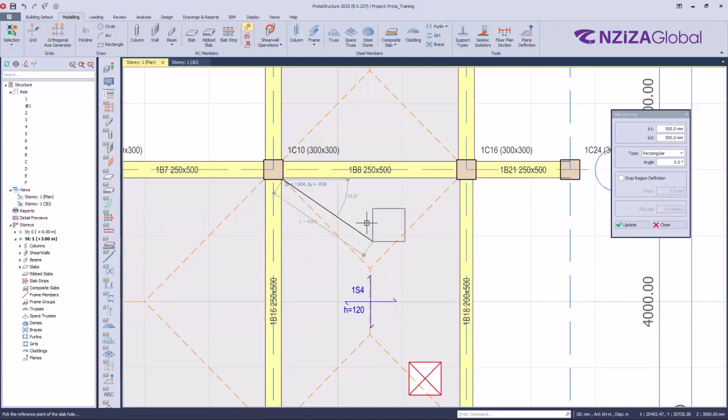Another thing here, when you press F2, you have the option to put the X value and Y value, from the point that you have taken as a reference. For example, if this is a reference, then I can put the value, say 2 meter as X, then comma, put the value of Y, 2 meter again, and click enter.